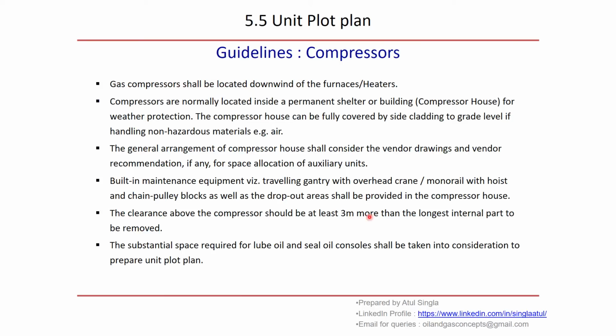We will discuss in detail how much space is required above the compressor, because inside the compressor shelter, if we have an EOT to do the maintenance activity, we have to allocate proper space for the movement of the EOT. How much elevation is required, and what the width and length requirements are, we discuss in detail in the compressor design section.